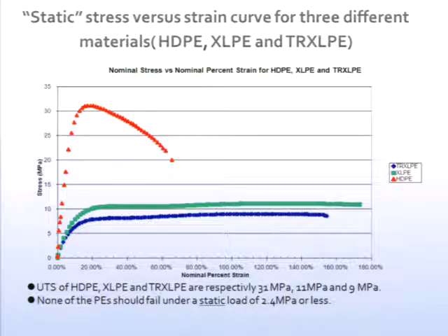So this is for a constant strain experiment where we're separating those grips gradually at a fixed rate, and then the stress increases quite rapidly to start with, up to about 5 megapascals. This is a case of cross-linked polyethylene, and this is tree-resistant cross-linked polyethylene. And I wouldn't claim there's any significant difference between those two.